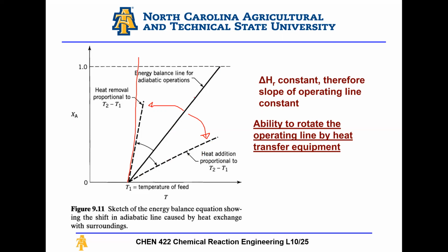And again, for exothermic reactions, you want to operate as close as possible to isothermal conditions, because even though this idea of moving along the locus of maximum reaction rates is technically valid, you want to do this if you have a reactant which is very, very expensive, or very dangerous, and you want to get rid of it and react it efficiently and quickly, while minimizing recycle. Then yeah, you want to play with the temperatures to keep the reaction rate at the maximum possible rate.